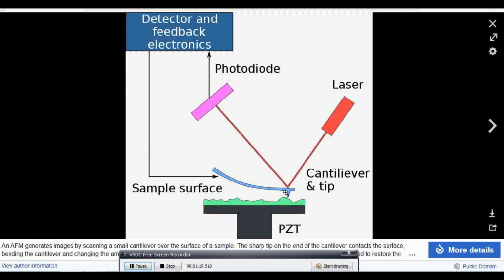That means this cantilever tip will have a force amount at atomic level, and then the positioning of this laser beam on top of the cantilever tip will be used as a reference, and also intensity and also topographical information data. So the laser beam is positioned on the tip when the sample is moved across.